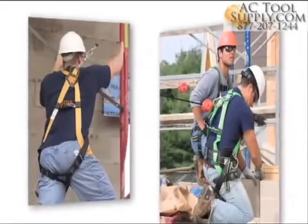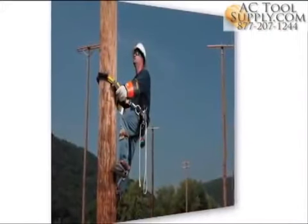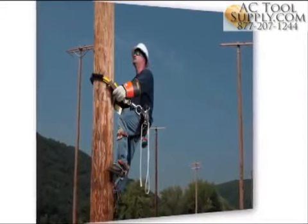Use only the back D-ring on a full body harness for fall arrest. Other D-rings are for positioning and restraint only.